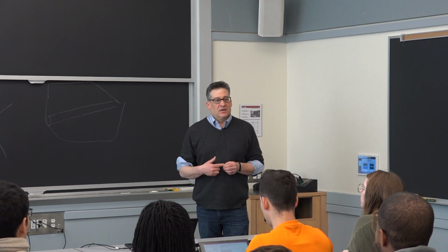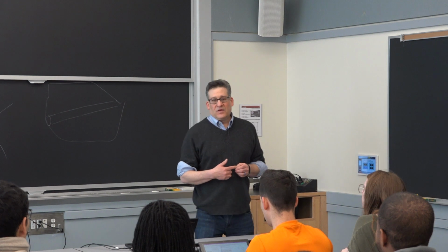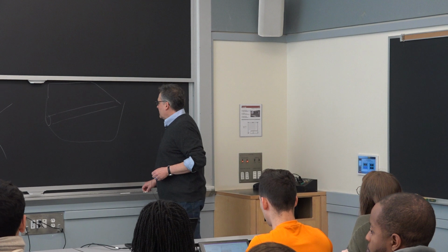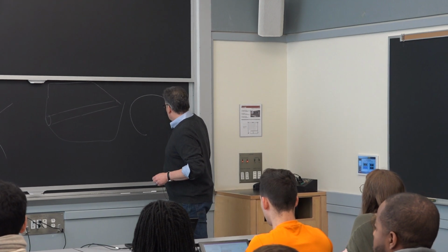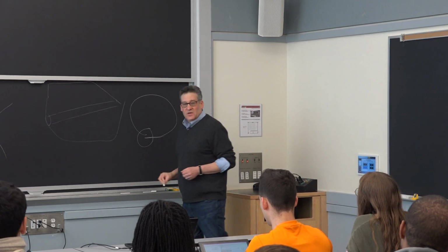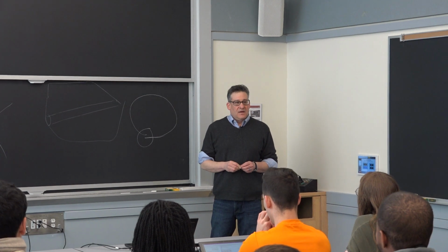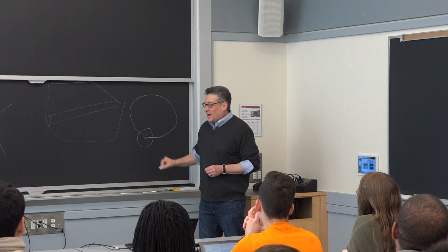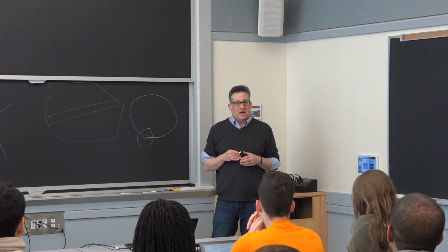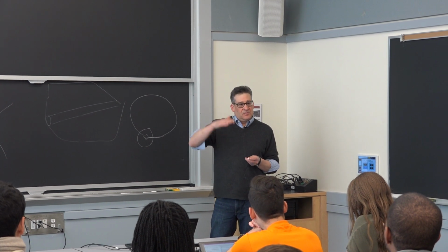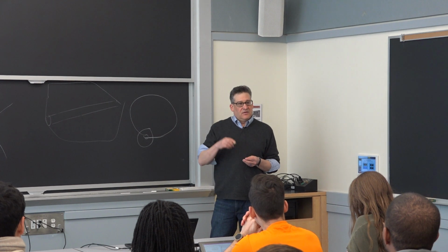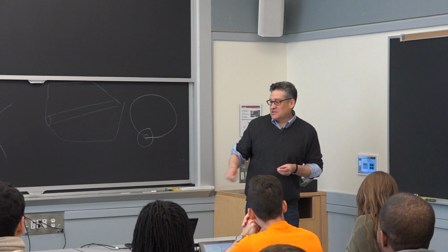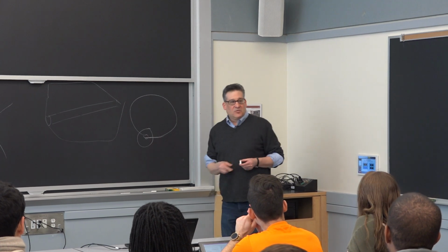Here's another one that's interesting. You think of tire construction. So when tires are made, they have a casing that wraps around. And there's always a little tiny bit of overlap right here where the belts and the tire come together. And as the tire is going down the road and spinning, you hit this little overlap, and all of a sudden the wheel's not round there, and you get a little input into the body structure, little vibration. As you go faster and faster, that frequency goes up because this little overlap and bump here is hitting the road more often.